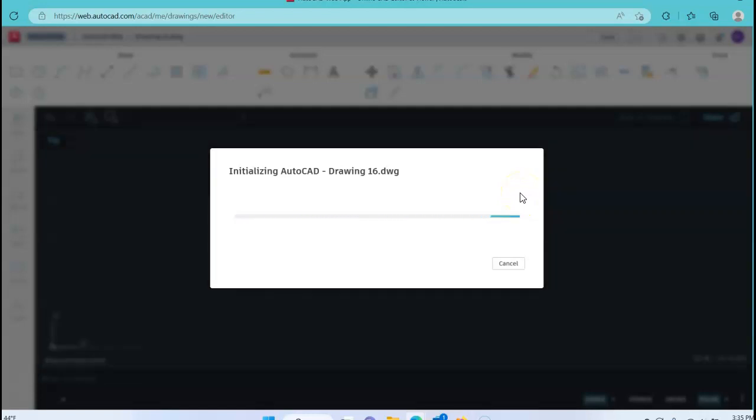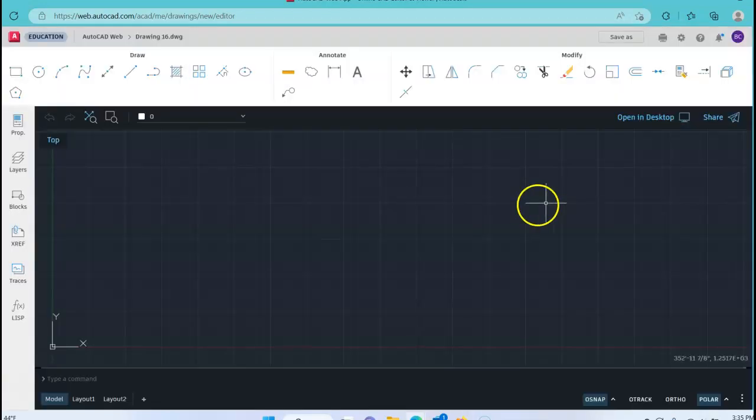Again, the same thing. We will get into a routine as we start up on each of these drawings. So we'll go in, we'll create our units. In the full version of AutoCAD, we'll set limits. We'll kind of take care of some of the settings that we need to, and we'll create layer properties. We'll get all of that done at the very beginning to get us started.